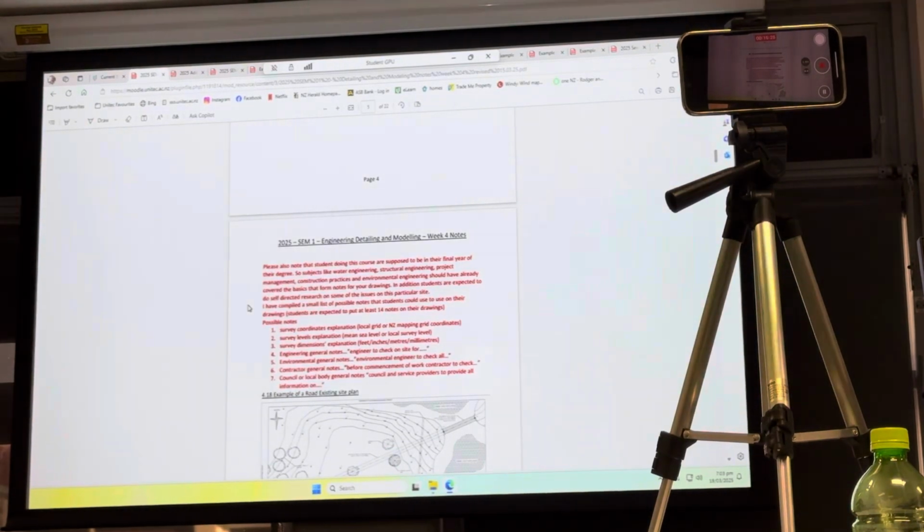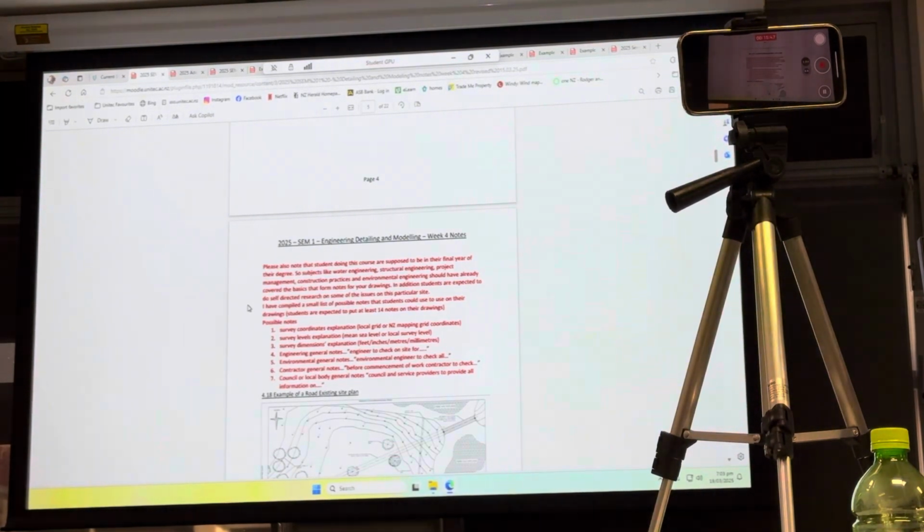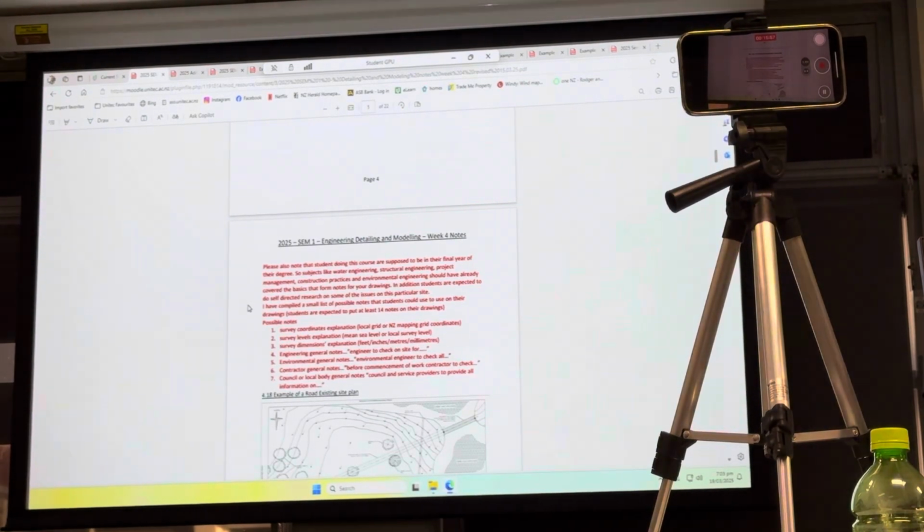Yeah, it's going to be 1.7. I can't tell you yes or no, it's an assignment, but if you've done the maths correctly, that's what it should be. Remember 1 to 500 isn't bigger, it's smaller. 1 to 1,000 is even smaller. 1 to 2,000 is huge in size. 1 to 200,000 is very tiny. You're getting your scales mixed up with size.